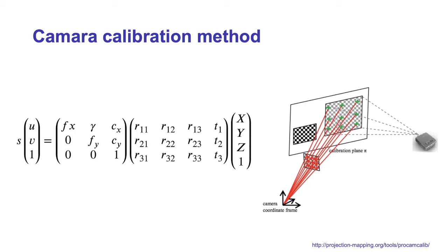Camera calibration can be performed using the OpenCV calibration packages in MATLAB. To calibrate the camera, multiple images of a calibration pattern are needed from different angles. Various checkerboard patterns can be used for this purpose. One of the main limitations of camera calibration methods is that they require one-time access to the target object to install the calibration panel. This access can be difficult in the field.